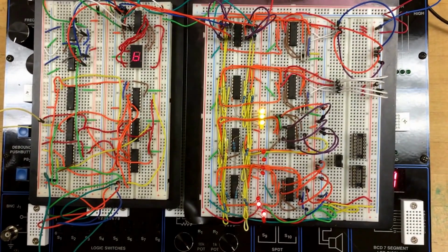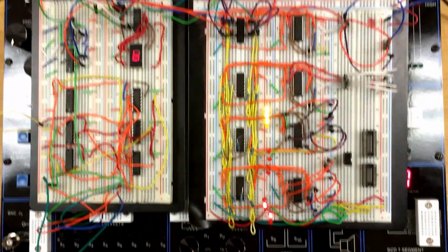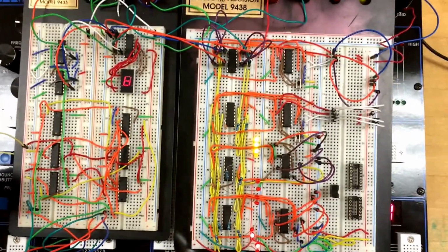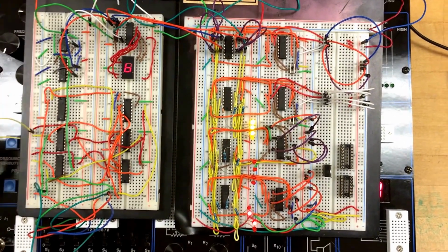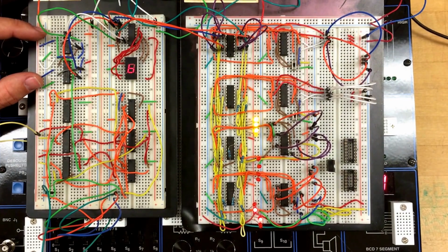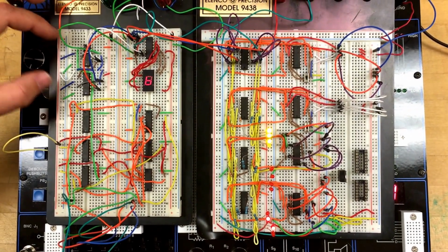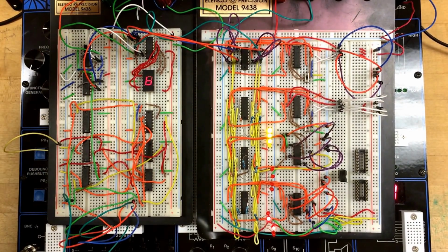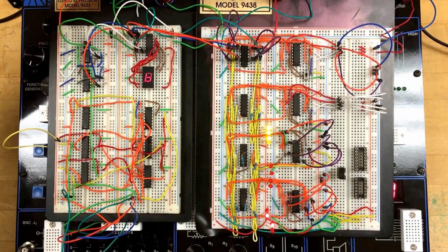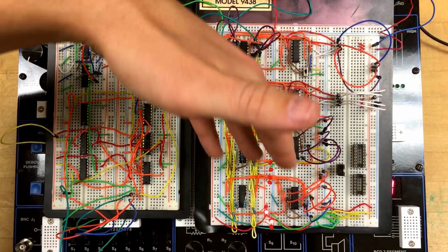Here we have a fully implemented circuit comprised of a loading area where we have a shift register made of D flip-flops, some AND and OR gates. We also have a storage section made of D flip-flops where our data is stored. After our data is being input into the storage unit, it goes over to our encryption and decryption stages. Here we have 2 encryption stages and 2 decryption stages.